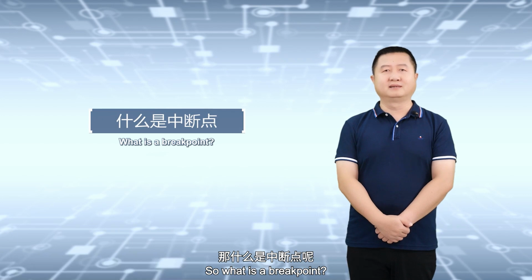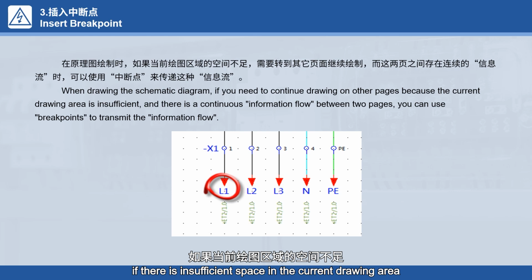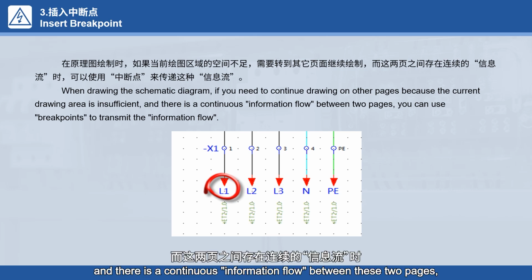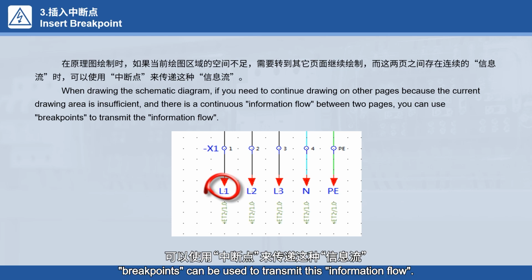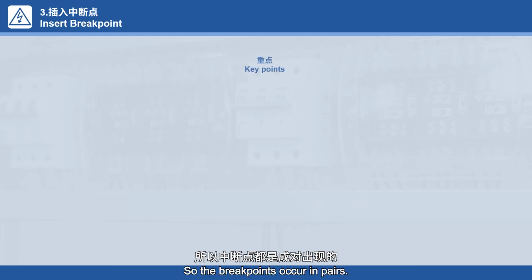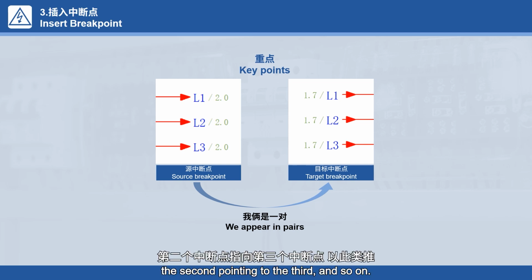So, what is a breakpoint? When drawing the schematic diagram, if there is insufficient space in the current drawing area, and it is necessary to continue drawing on other pages, and there is a continuous information flow between these two pages, breakpoints can be used to transmit this information flow. So, the breakpoints occur in pairs. The paired breakpoints are composed of a source breakpoint and a target breakpoint, with the first breakpoint pointing to the second one, the second pointing to the third, and so on.